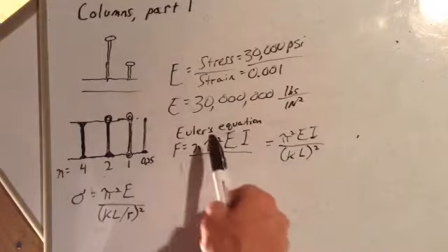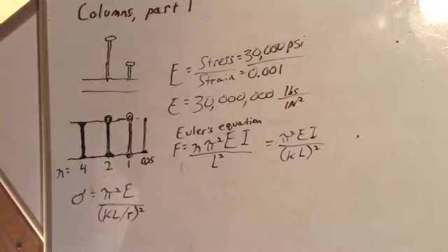Well, when you're talking about a beam cross-section, you're talking about area radius of gyration, and you could describe it with almost the same words. You could call it the radial distance from a given axis, a centroid axis, at which the area of a body could be concentrated without changing the moment of inertia of that body, because moment of inertia is area times the square of its distance to the centroid axis.